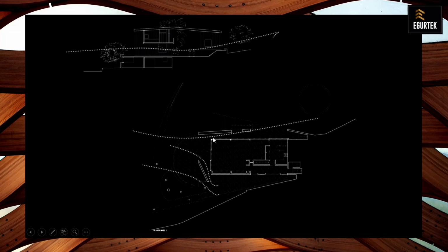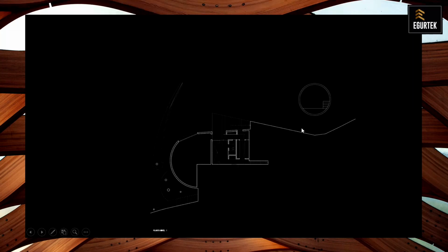And this also overlooks the ascending drafts. So there's an increase in the wind speed and there's lateral ventilation. And well, this line goes this way and then goes up. And in the upper section, there's an outlet. So air can enter through the eaves to remove the air that's inside, so the house works perfectly well, thermally speaking, thanks to this constant ventilation.